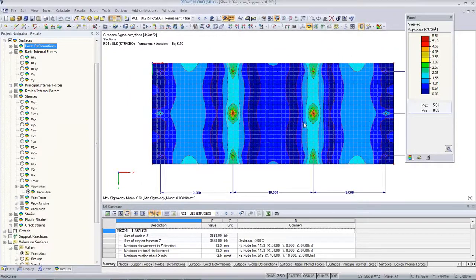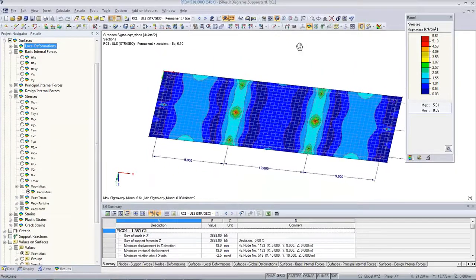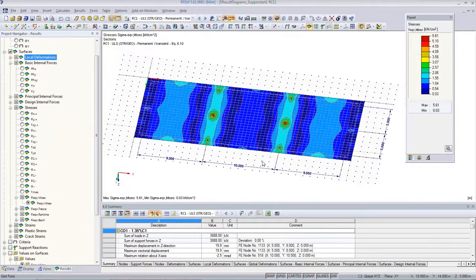So first of all, how to find singular points, how to find problematic points. Well, typically it's locations where there are high stress gradients. So if you make the mesh dense, you will get an infinitely high value, and it's very steep. You will have a very steep angle in the change from one finite element to the other one. I can show you this. For example, if I make a section, a longitudinal section. Let me do this first.